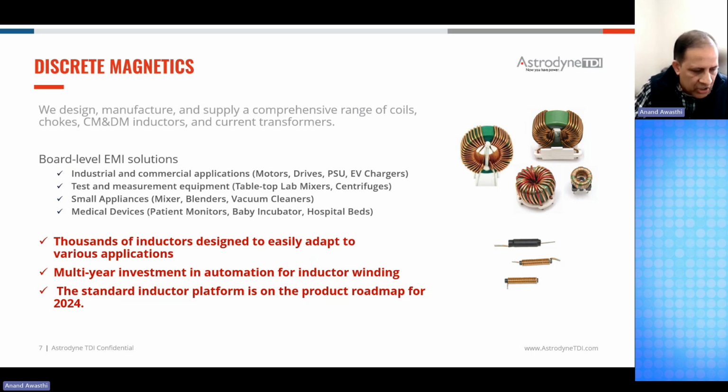I work very extensively with these customers. Sometimes it's MIL-STD-461, CE102, sometimes CE101, for types of applications where you're looking for a differential mode inductor to suppress your low frequency harmonics. And trust me, more often than not, I am able to pull a design out of my repository that was done 5, 10, 15, 20 years back, that is effective in that application, and I don't have to redesign it. I can quickly give them a sample and go into manufacturing from there.